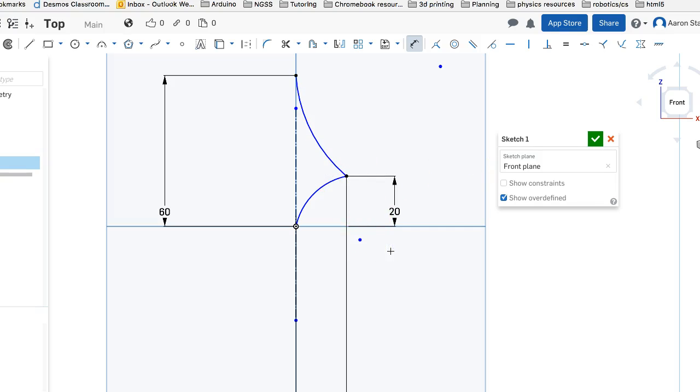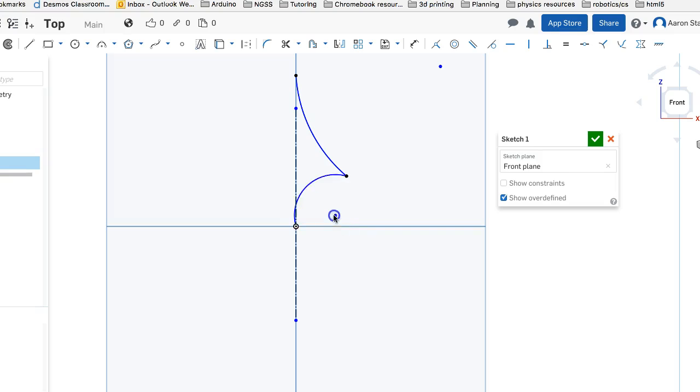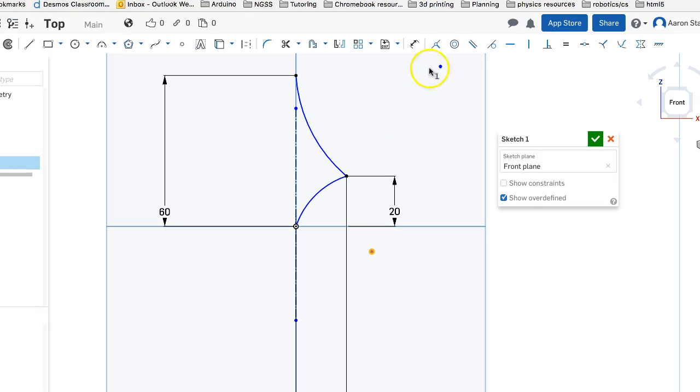And then we can kind of adjust how severe these angles are. So let's set this one, get a dimension tool, or this arc. We'll set this arc to be about, oops. So when we dimension the arc, we click right here, and it's at 31, which is pretty good. I'm going to go with 30, so we have kind of a round number. And then for this one, I kind of like the look of this one. I'm going to make it a little bit more, so I'm going to go with 60.